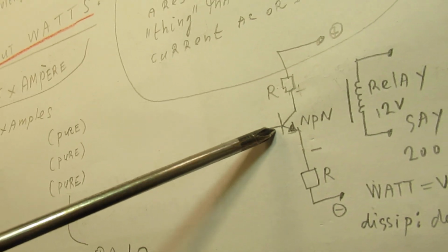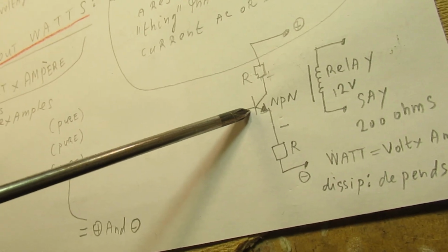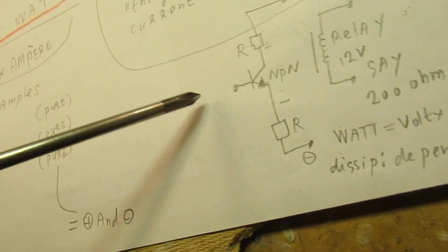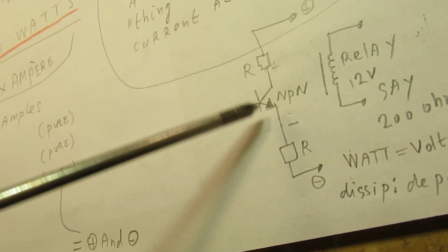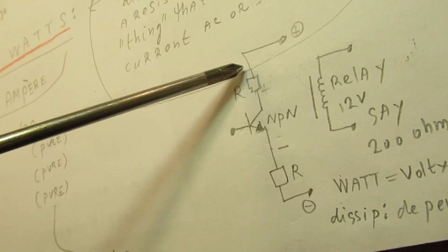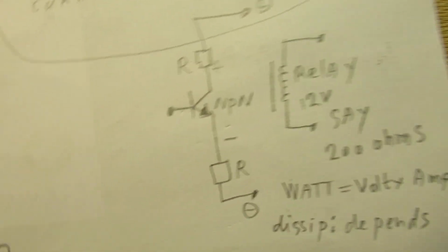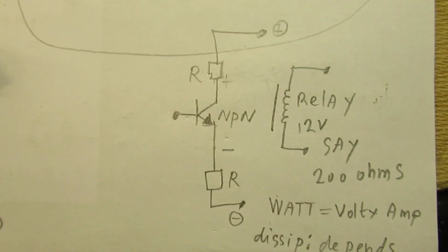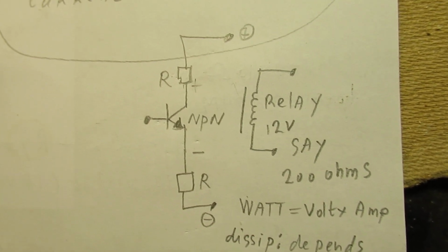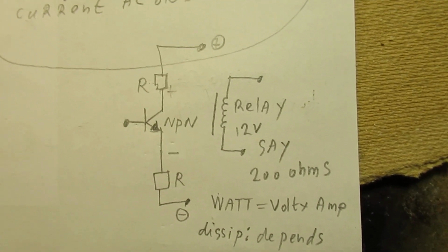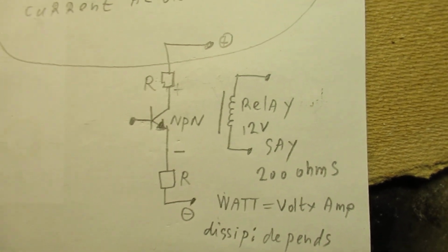And when that current is too high, the transistor will be damaged in a severe way. Anyway, so limit the current to the base in this case, and then you can calculate the maximum current that can flow. Such a maximum current is more or less always in the datasheet. So you can use Ohm's law in that case.